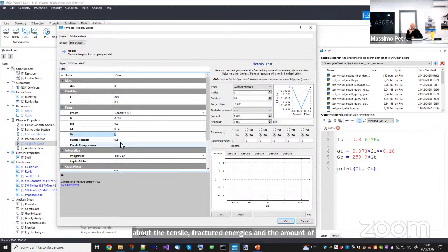So one thing that I typically do is that, okay, it is a frictional material pretty much like concrete. It is less precise than concrete. So I will try to first use the equations that I have available for concrete, and I will use them as an upper bound. And then I try to lower them, trying to calibrate these parameters.